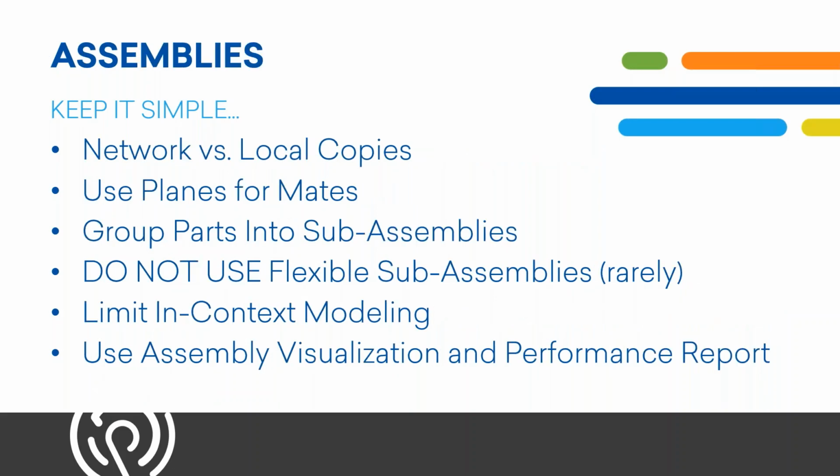Finally, we're here at Assemblies. If you're working on an assembly with other people and your company does not have PDM, we understand that, but we recommend that you work with primarily local copies of your files. If you're going over a network, there's a lot of communication that happens between part files, between assembly files, all of SOLIDWORKS. When you're working with either assemblies or drawings, there's a lot of communication that has to go back and forth. If it has to travel over your network, it will only be as fast as your network, which is a variable that we can't control.